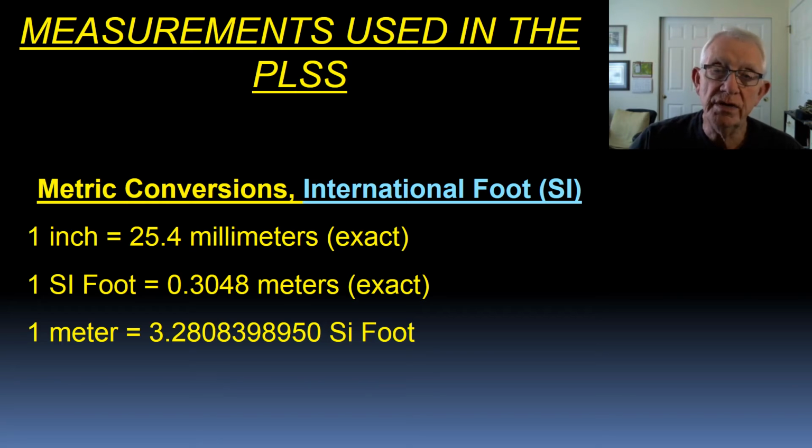So those are the things that we wanted to show you. They're in the Manual of Survey Instructions 2009, and we just need to be aware of it. But you as surveyors pay particular attention to the US survey foot versus the international foot, and make sure you're using the proper one for your calculations and your particular state. Now, when you're working in the public land survey system, you're going to be using the US survey foot. But before you do, I would suggest to you that you download the PDF file for the second lecture and you keep that with you so you can take notes.